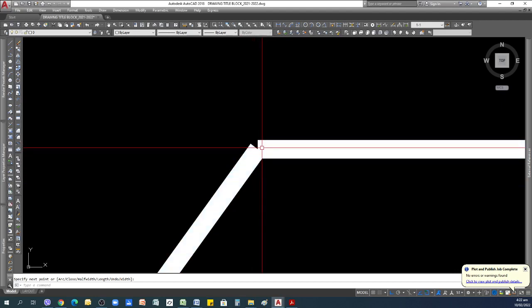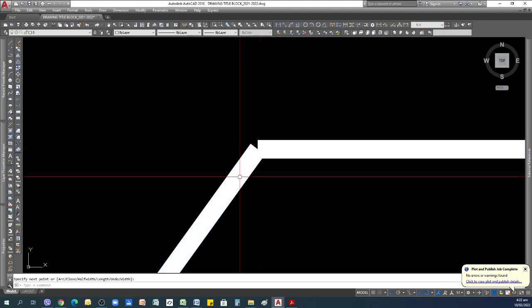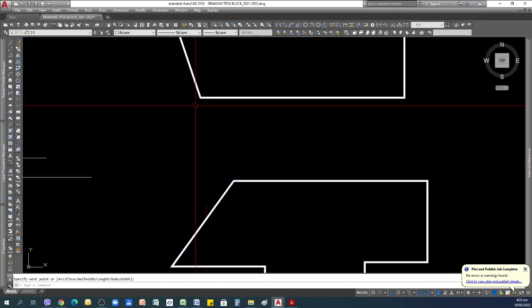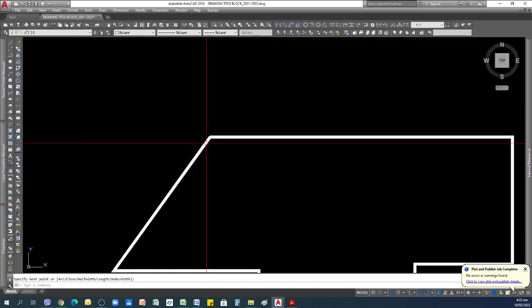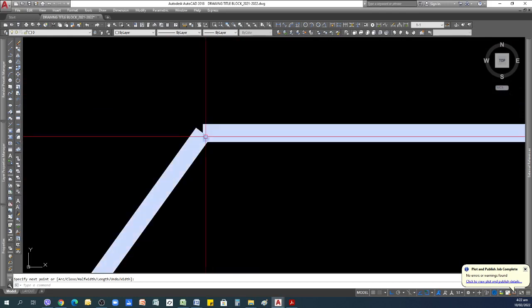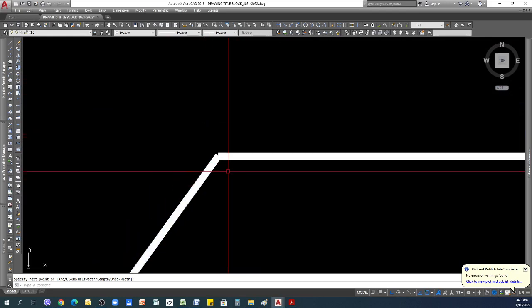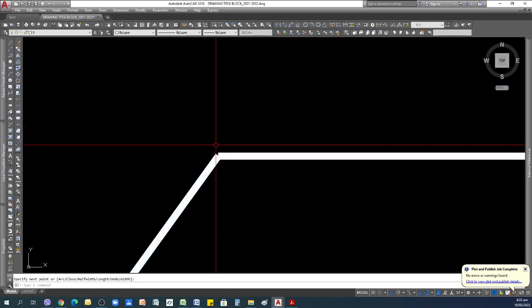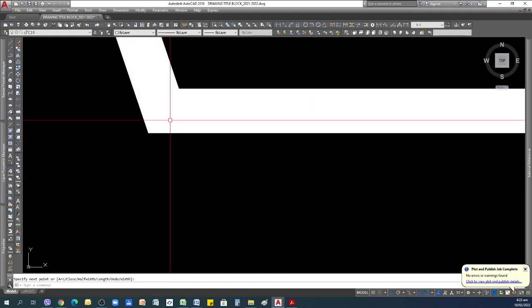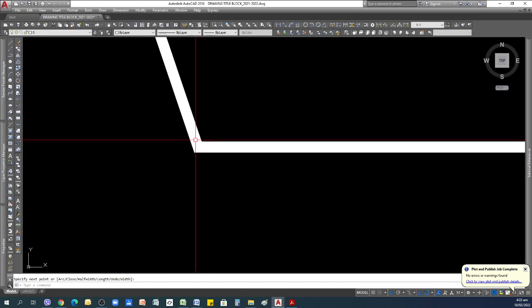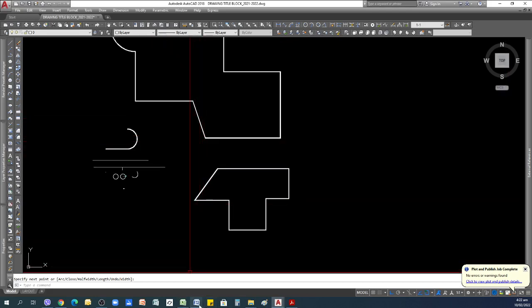They meet each other only at the starting and end point, but they are not closing the same way as this one. So that's the difference between just clicking the end point with your starting point against using C to close the shape of your object. Okay, so that's PLINE.